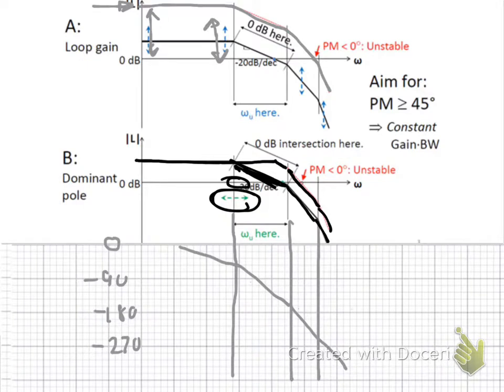We can therefore increase our phase margin and increase the gain margin, because of this new pole that we have introduced, our system behaves differently. We've got a different 3 dB cutoff point, because the pole that we introduced is dominant, and it will dominate the amplifier characteristics.